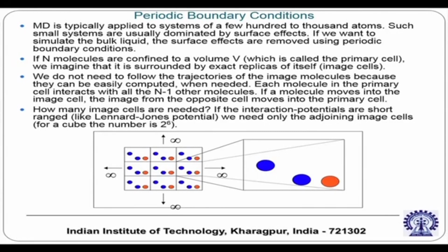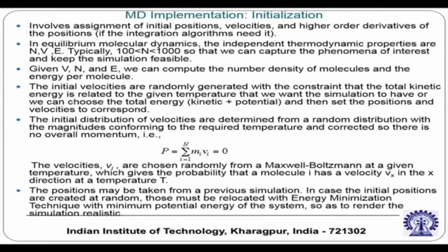So it is basically repetitive behavior of some monoblocks, where each monoblock is a unit cell type of thing, and you basically consider that whatever is the boundary condition at the inlet, for example, at the outlet of the repeating unit the same boundary condition is repeated. So that is called periodic boundary condition.